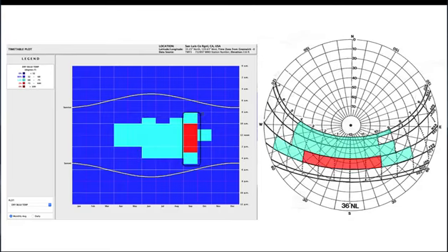So we're going to shade from 8 to 10, which is comfortable, right here, and then from 10 to 3, it'll be too hot, so we'll make that in red, and then again from 3 to 5, that'll be comfortable. So we're going to go through this process until we've shaded everything that's either turquoise or red, and we're especially going to note this red area where we're going to need sun shading.